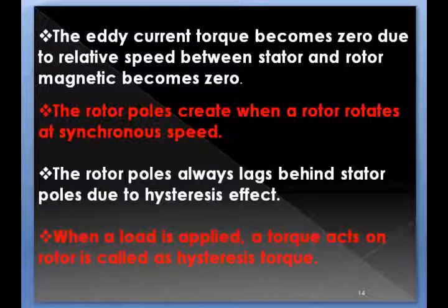So there will be no eddy current induced in the rotor. At that time, the rotor rotates only by the hysteresis torque.